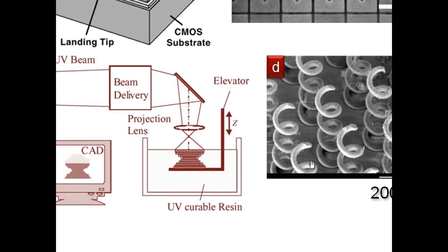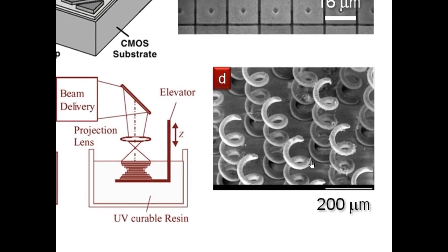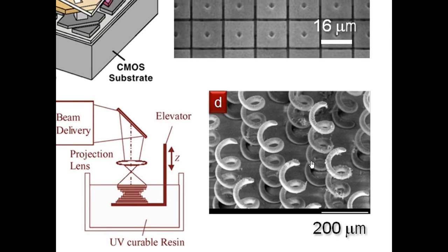So these are examples of some very beautiful three-dimensional patterns that you can get by using this lithography process. Now, there are a few big differences between this micromirror type device and traditional photolithography. First, you notice that you don't need a mask. The micromirror is creating the pattern of light and dark for you, rather than having to print a mask. So that's great.